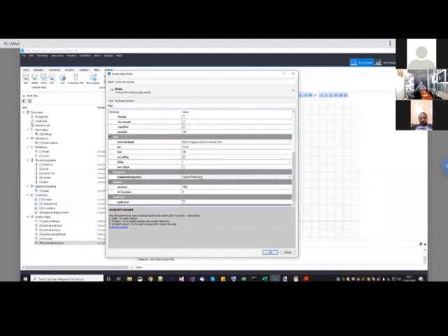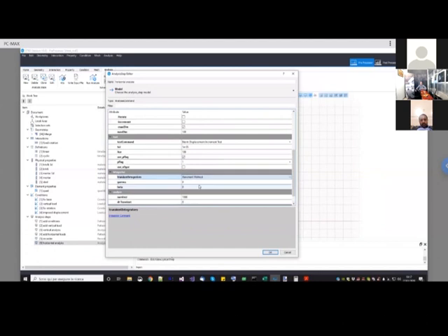By default it is the central difference, which is explicit. If you are not an expert of explicit methods, let's change it. You can use, for example, the Newmark method. You choose the Newmark parameters that you want. By default, it was 0.5, 0.25. And you can choose the number of increments and the time step, which is the real time step.